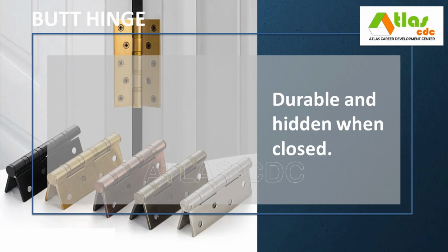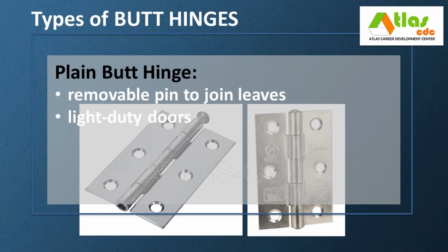Butt hinges are known for their durability due to their robust construction and ability to handle heavy doors. They are not inherently hidden when closed, though some designs, like those with non-removable pins, can offer increased security. Butt hinges are traditionally visible when closed, with the knuckle and pin assembly exposed. Plain butt hinges use a pin, which is sometimes removable, to join the leaves together.